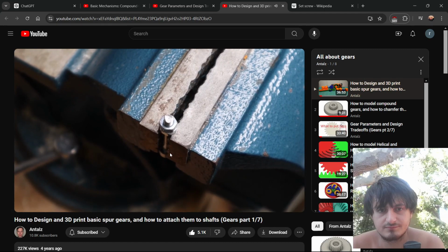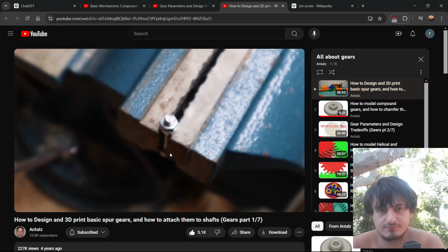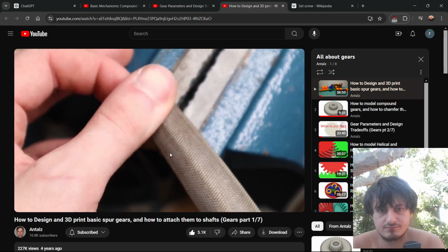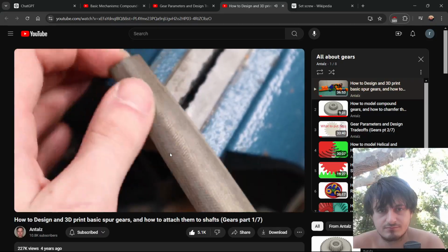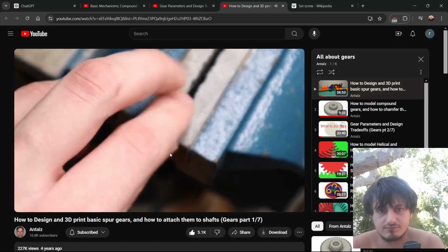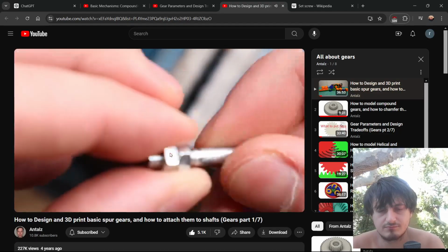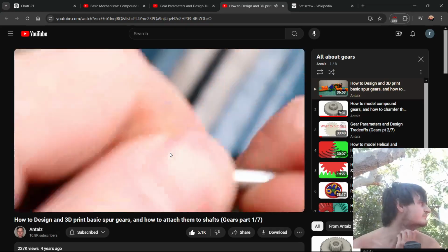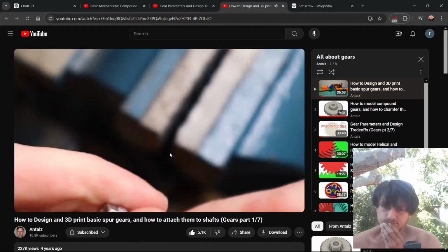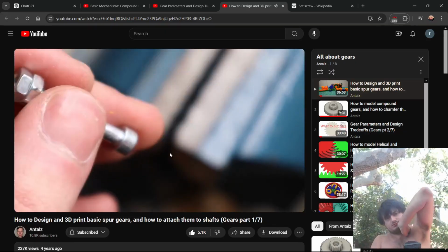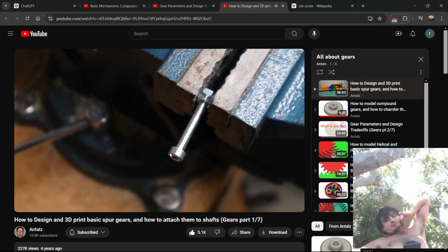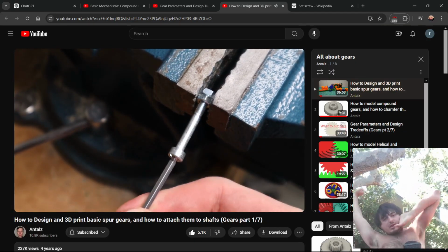I'm not completely happy yet with this screw because there's a slight sharp burr here that I want to remove. So I've put 2 nuts again on the threaded section, and I can just take a file and get rid of that little nubble that I do not want. So that's smooth now. And then I can take the screw out of the vise again, and again threading the nuts back over the piece of thread that I just damaged. This doesn't work. So I will need to use my pliers instead. I misspoke, of course I'm not going to use my pliers, I'm going to use my vise.